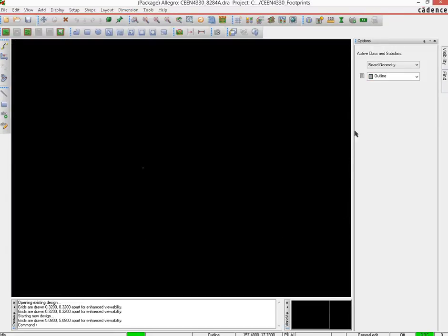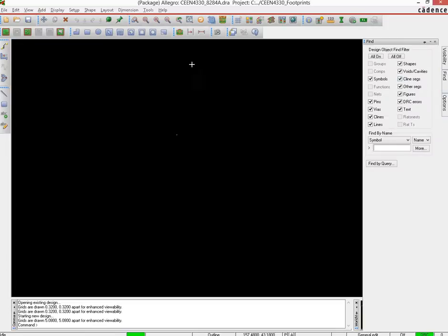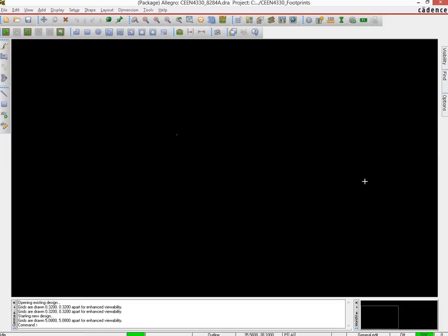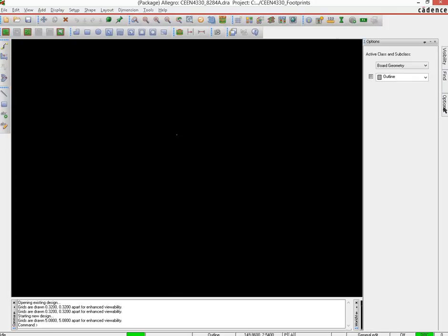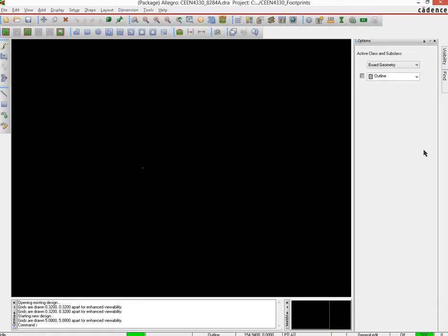Now this particular window on the right hand side is a context specific menu which you may be seeing or may not be seeing. Notice this little pin over here. If I click it, it disappears, so you would probably be seeing this view right now. Now this context menu is very important, so it's better to keep it displayed always. So go to this options page, and then you can hit the pin here, and then it will get fixed there for good. So that's the first thing.